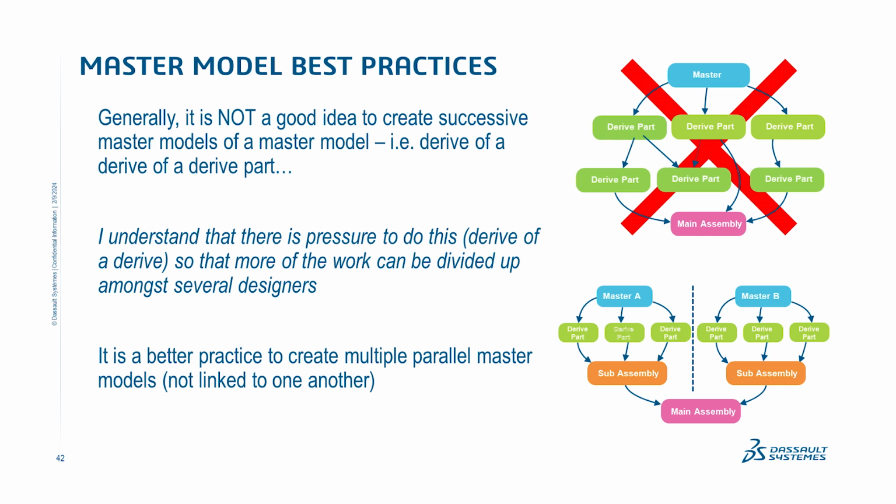Well, you can imagine how confusing this can be and why so many people object to it. When groups don't use master model correctly, and they do this, it becomes a mess. It also leads to more potential error, because when you have multiple derived parts on top of each other, it's just going to exponentially increase the amount of error that could occur.